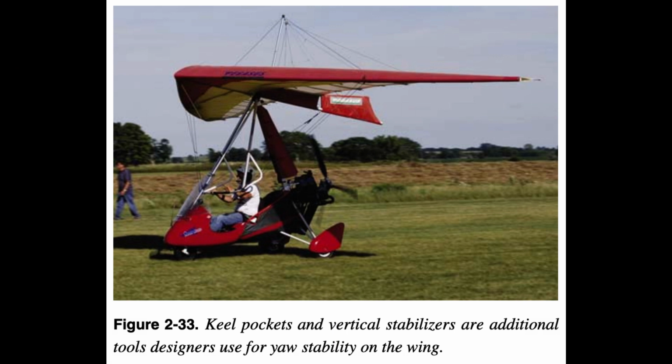In addition to the wing platform, twist, and airfoil shapes to minimize yaw, some wings utilize vertical stabilizers similar to these in airplanes and others use tip fins. Figure 2.33. Generally, the WSC wing is yaw stable with minor variations that are different for each wing and can be controlled by pilot input, if needed.